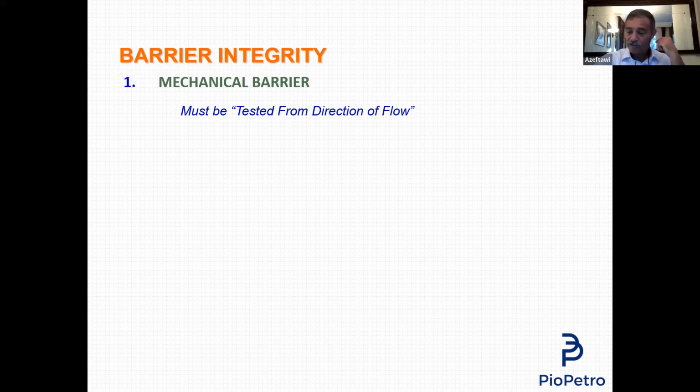Some of you will not believe me. So what they will do is, after we finish the lecture, you will go to the yard, take your BOP, close your blind ram, and then put 3,000 psi from the top, and it holds the pressure. Then in the following session, next Sunday, inshallah, you will show me the chart recorder graph. Come on, Ahmed, I tested the BOP from the top, and it holds the pressure for 30 minutes from above. I said, yes, I believe you. I believe you did that.